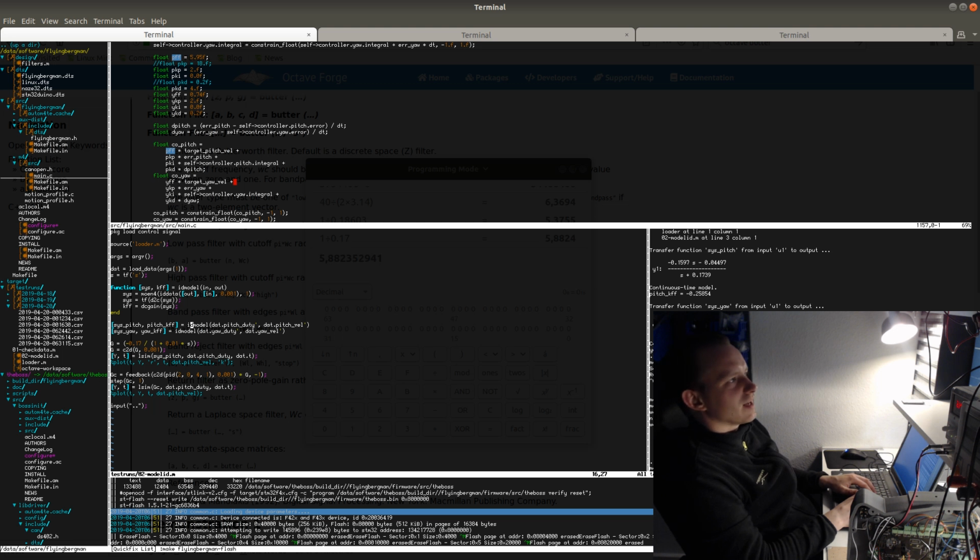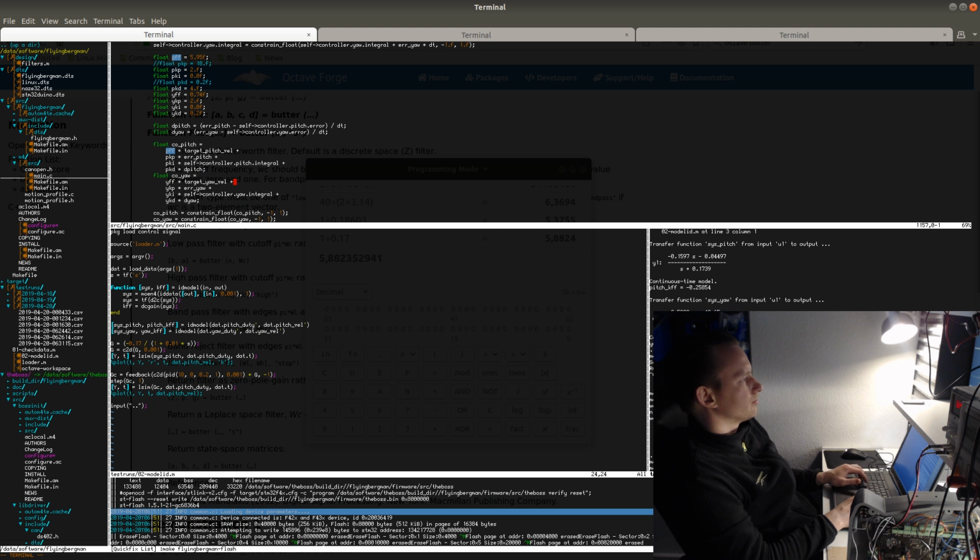It will never behave exactly as the model in the real world, but the model can give us a good feel for what is reasonable for this system. And setting the D value to 4 is way too much. 0.2 is more reasonable, and I'm using 18 as the KP value, which I've arrived at based on a little bit of experimentation, and also looking at the produced plot here.